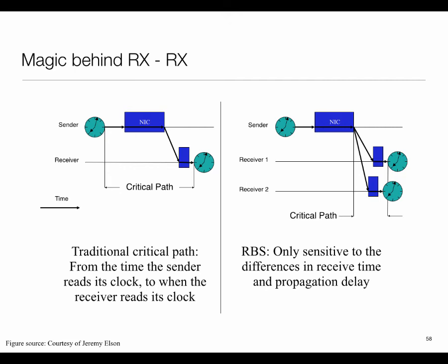But the main thing that this scheme combats is that it doesn't have to worry about uncertainty of timestamping on the sender side. Sender side doesn't have to timestamp at all. In fact, you don't even need a sender. This trick can be done using any other thing that all receivers can sense. It could be a loud sound. It could be a flash of light. It could be any common event that all the sensors have the ability to sense and uniquely identify. The reason a radio packet works is because we can embed a sequence number in it, so you can say, I saw the packet of this type with sequence number so-and-so, and that's the timestamp. So it's easier done with radio packets, but it could be anything.